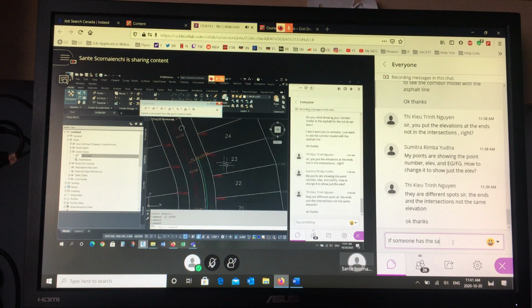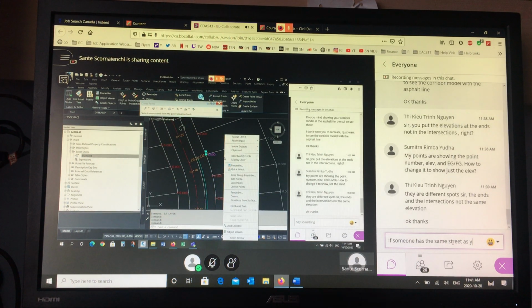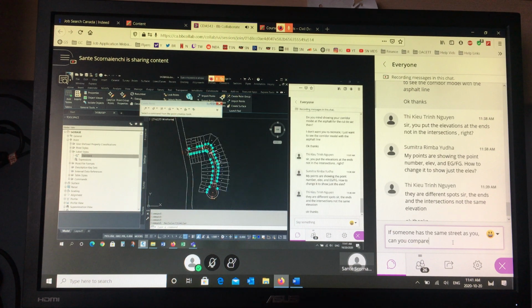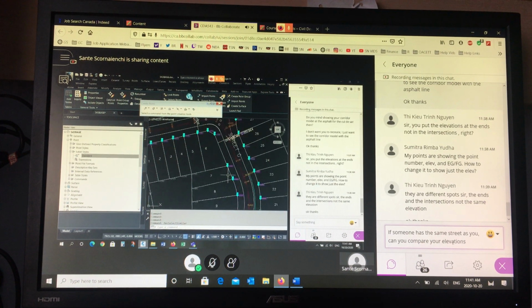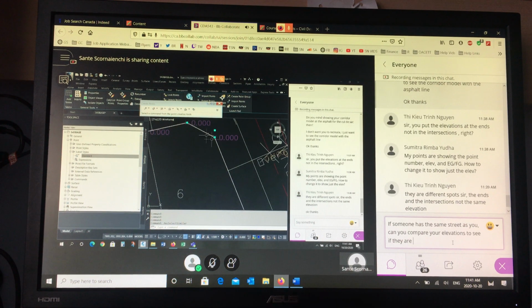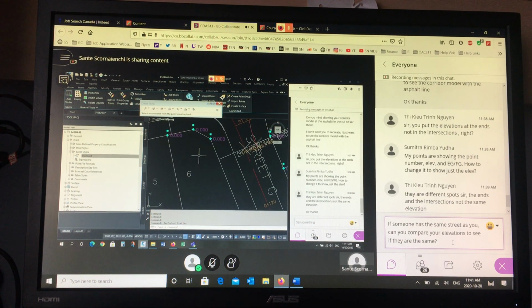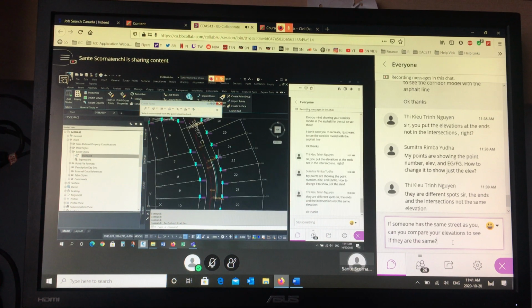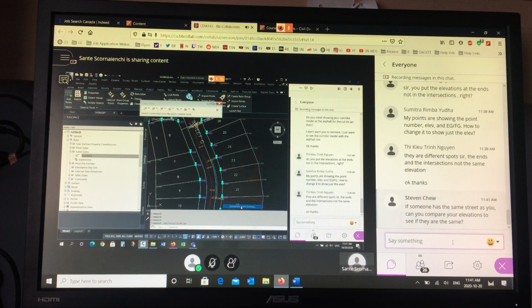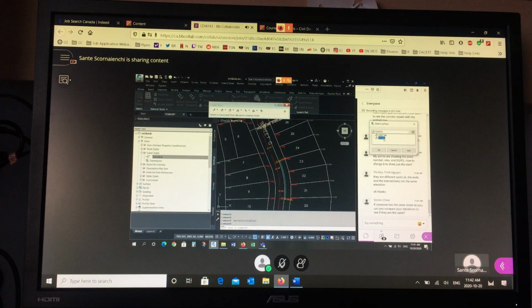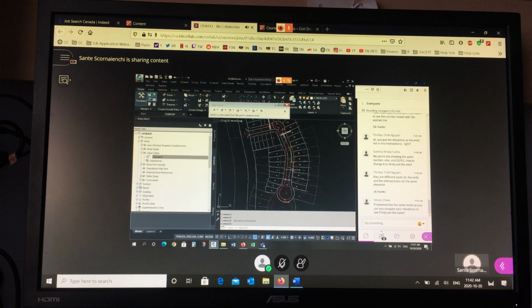So watch this. If I click on one of these and I say right click, select similar, I grab all of them. Right? These are all my elevations at the front lot corner. Don't forget these 2, right, on this triangle inside the site. If I right-click and I say elevations from surface, and I use my proposed road, no, you can't, because you have different surfaces. That's the whole point. Say OK. Now I have all my front lot corner elevations. And I don't get lost in the numbers.